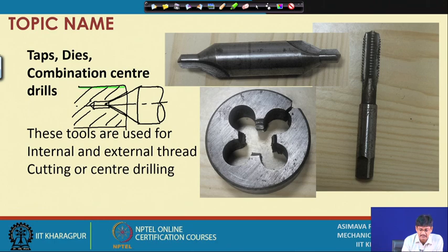I mean the axis of this center and the axis of the body which is being held will become aligned together. Moreover, since we are offering some latitude here, there can be some bending, so that when you are doing taper turning and other things, this will not be indenting it at a particular corner. So, some latitude is there, you can fill this up with lubricant, some sort of lubricating material, so that friction is less, and this hole can be done by this one.